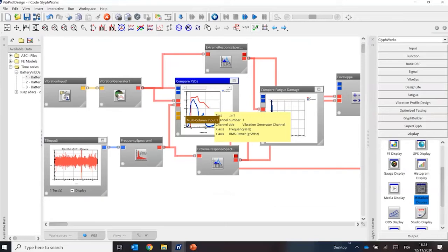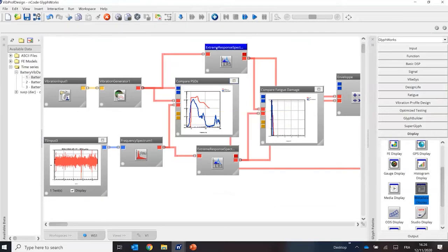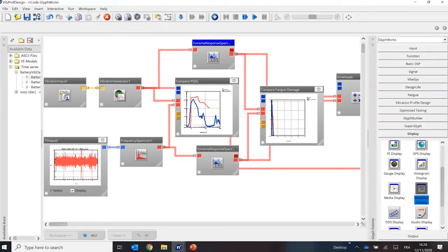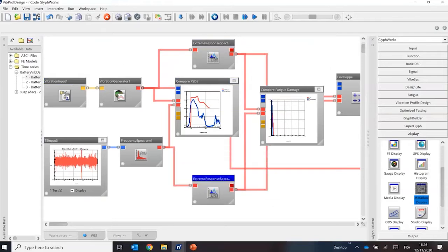That's really comparable. So what I did here, I produced what's called the fatigue damage spectrum for the standard spectrum from the standard, and I did the same for the spectrum from the measurements, right, from the measured data. And I take into account the duration of this red spectrum here. And in here, I'm saying that my whole measurement, my whole mission profile is actually, I can't remember, 30 hours or something. I wrote in there, yeah, 30 hours.